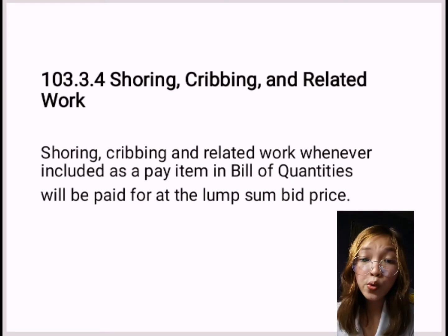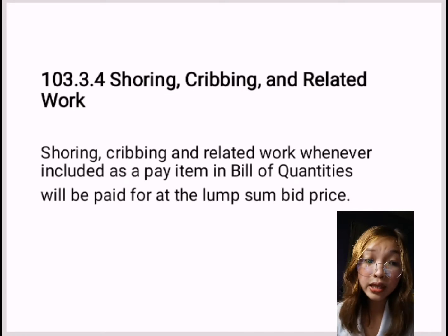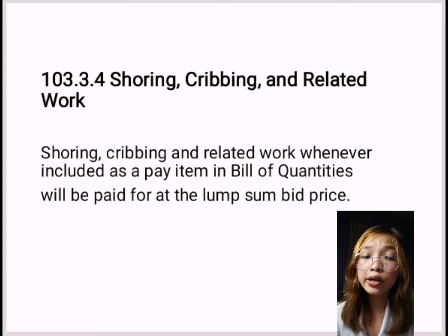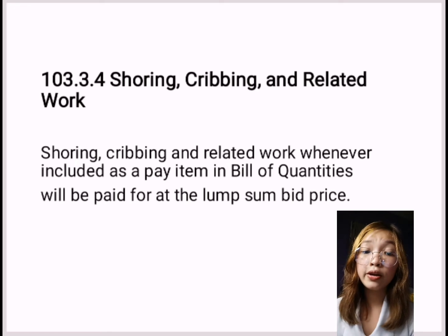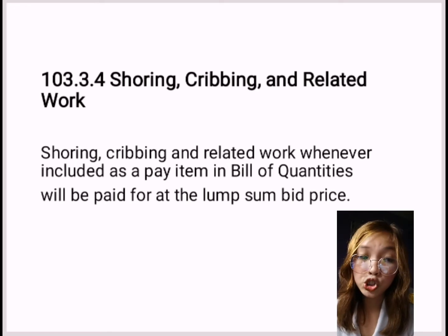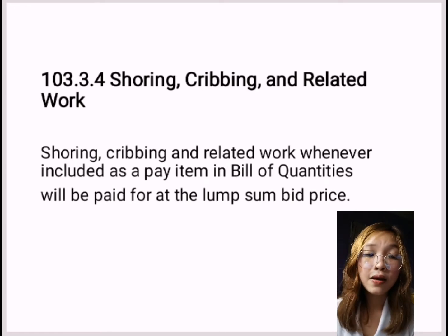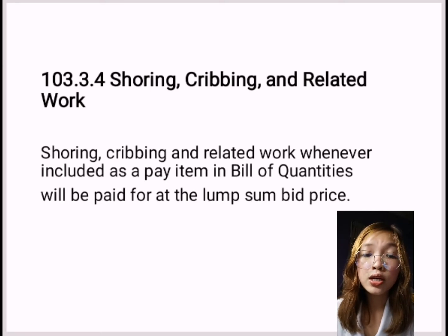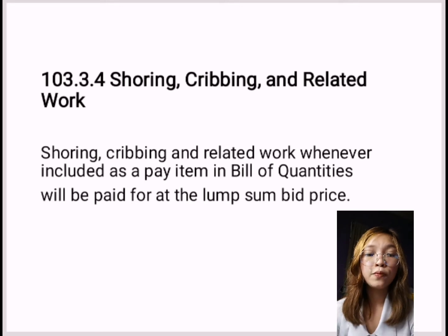So this work shall include furnishing, constructing, maintaining, and removing any and all shoring, cribbing, cofferdams, caissons, bracing, sheeting, water control, and other operations necessary for the acceptable completion of excavation included in the work of the section to a depth of 1.5 meter below the lowest elevation shown on the plans for each separable foundation structure.